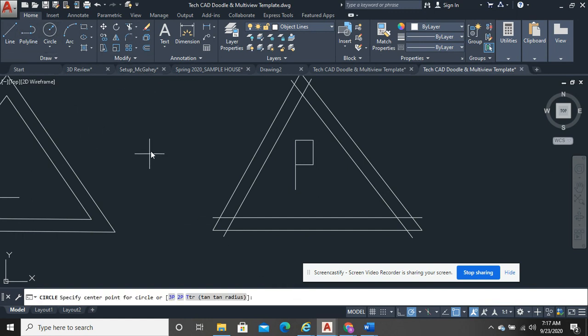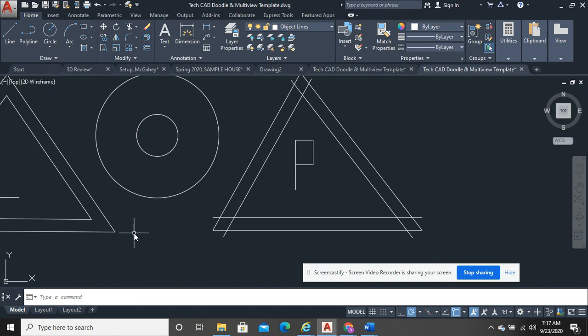So that's offset. Again, it's pretty simple. Pick anything you want to draw, right? Go ahead and tell it you want to offset. Give it a distance. Type in, let's say 0.5. Click here. Click there, right? You just made a target, okay? Or a donut.